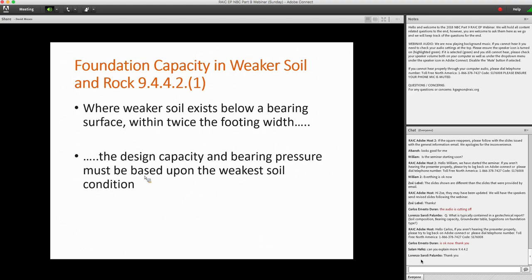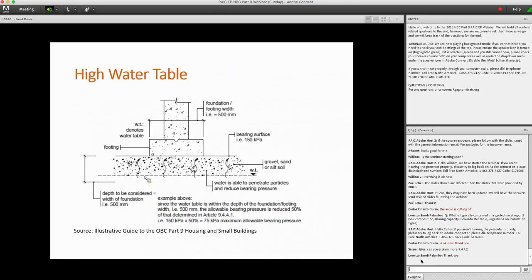But once the soil becomes pretty shallow, equal to a distance down the same as the width of the footing, then we could start using the capacity of the rock. That's kind of similar to what's shown in this image, but if you replace the depth of the water table, which is shown as WT, with the rock down below, same thing, except that we would actually be increasing the capacity of soils. Hope that answers that question.